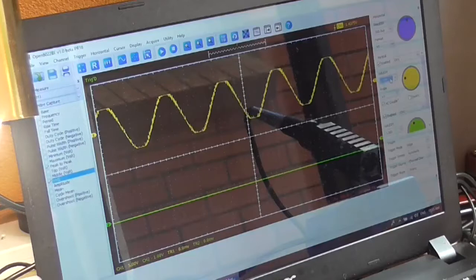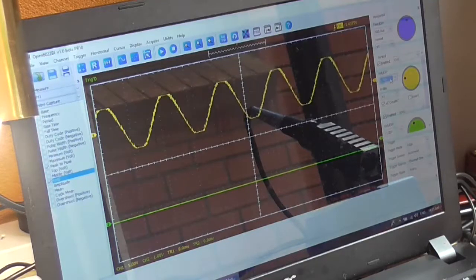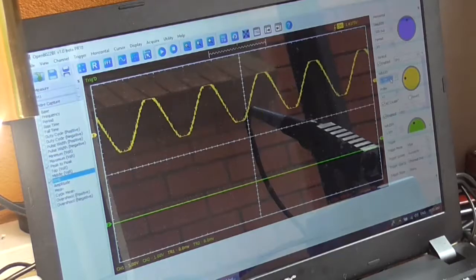So it looks like our input sensitivity is not that big to get full output. We're looking at 0.5 of a volt, and it's already clipping, and it's peaking out at 10 volt peak to peak. So it's not going to be producing much in the realms of output.